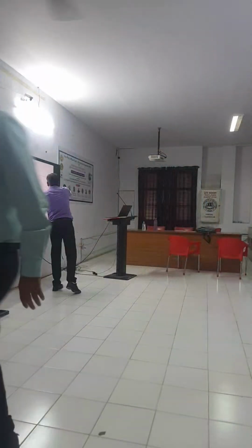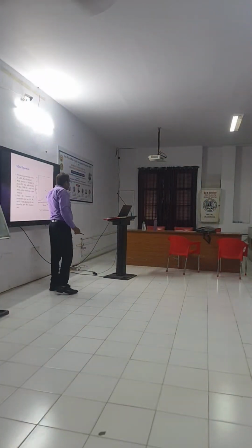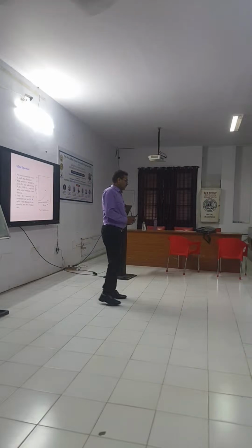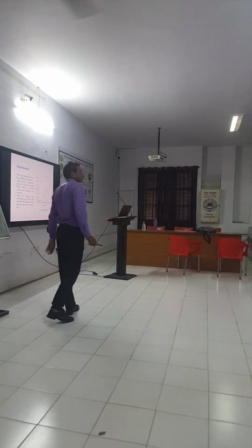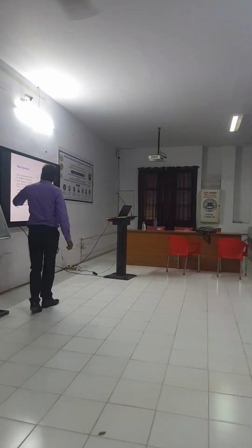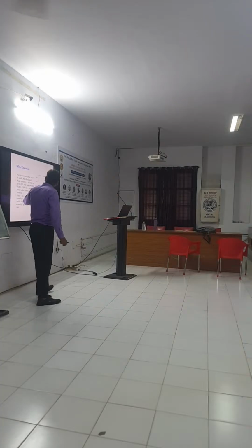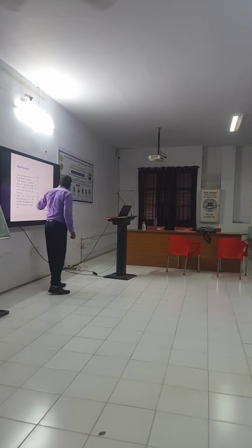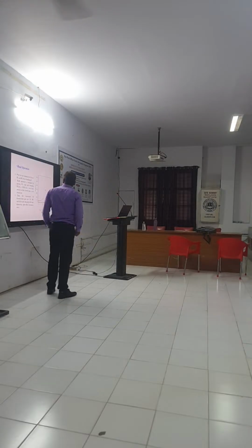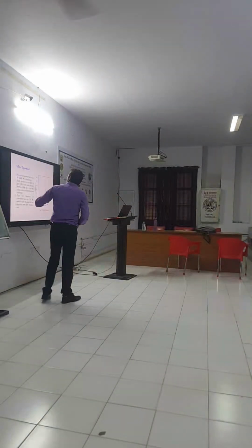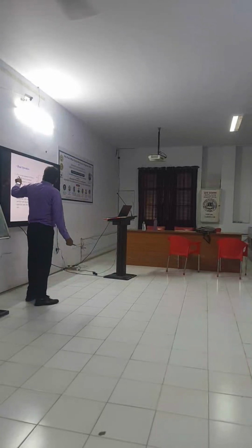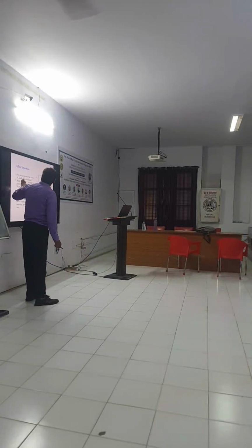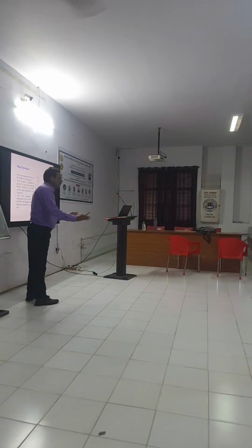So this is increasing. When this BL increases, that is connected with the other side. So this BL is increasing, and BL bar stays the same. In the same way, for the read operation, prior to the read operation, BL and BL bar will discharge to 0, 0.